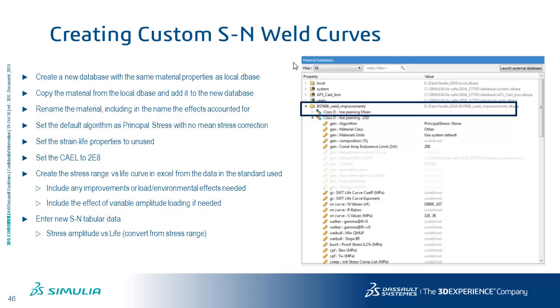And then you create the endurance curve, stress life curve. However, what is important here is that you convert data from a standard where it's presented as a stress range into the quantity that's expected by FESafe, which is stress amplitude. So essentially, as you read any stress data from either IIW or BS7608, you need to divide that value by 2 before entering it into our database. It's a simple process to do, really.